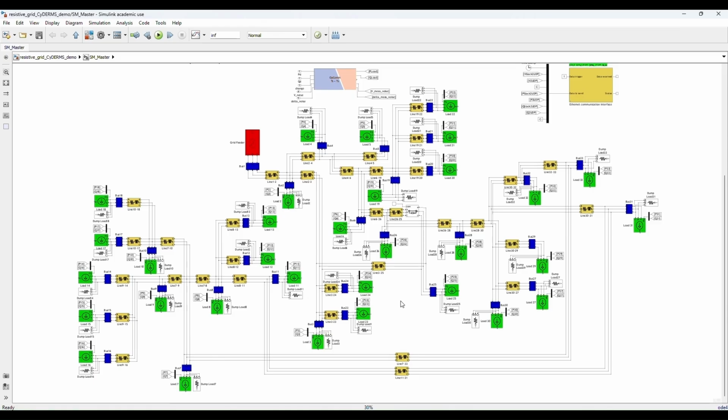During runtime, there are 33 emulated digital RMS meters which are measuring the voltage magnitudes of the buses. These measurements are then transmitted in real time to the emulated sensors via the UDP communication protocol. This concludes our description of the real-time simulation model.